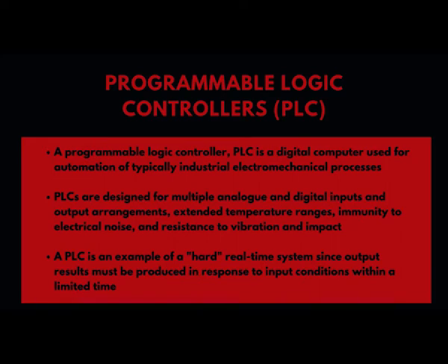A PLC is an example of a hard real-time system, since output results must be produced in response to the input conditions within a limited time. Let me elaborate a little more on PLCs. While the distributed control system measures the pressure of the compressor system, the flow of the compressor discharge, the level in the knockout drum, and the flow of the compressed gas, the programmable logic controllers primarily take care of the safe operation of the compressor.